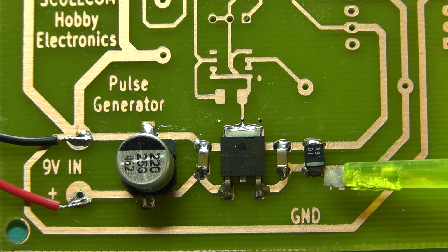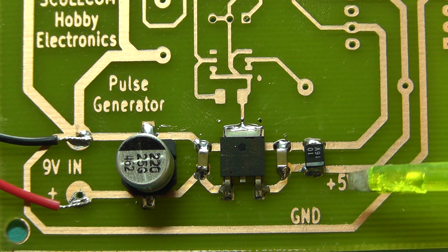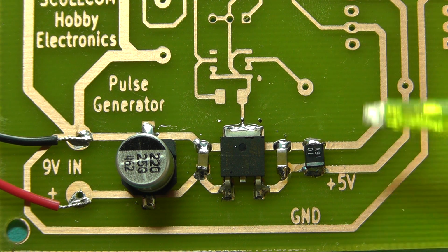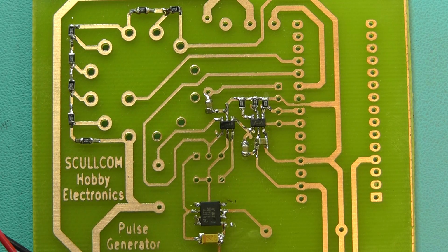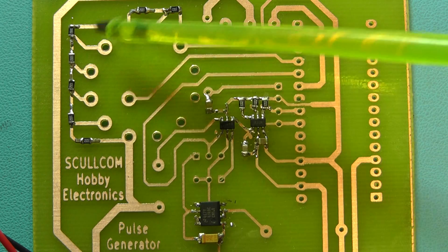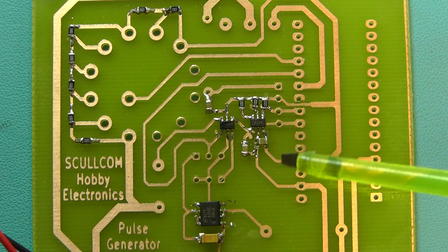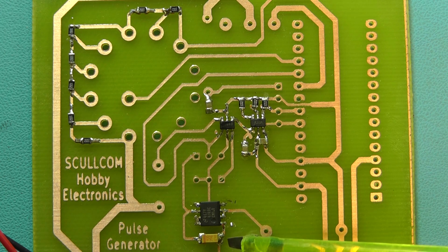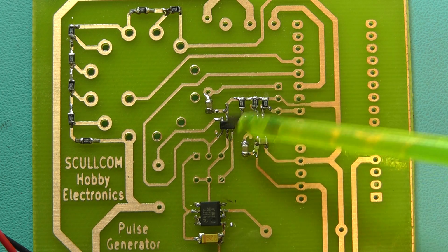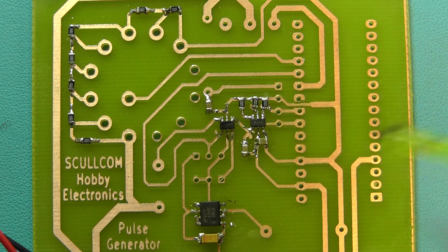So I think the next thing we'll do now, having satisfied ourselves that the 5 volts is okay, I'll mount the other surface mount components on the board, including the ICs. Right, we'll now have all the other surface mount components mounted. There's the 10k resistors which relate to the selector switch. There's the voltage reference IC, there's a 1 microfarad tantalum there, and the other components are around those two ICs there. I'll just zoom into that so you can see the layout of that.